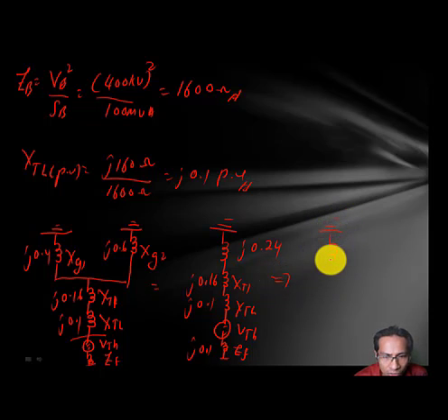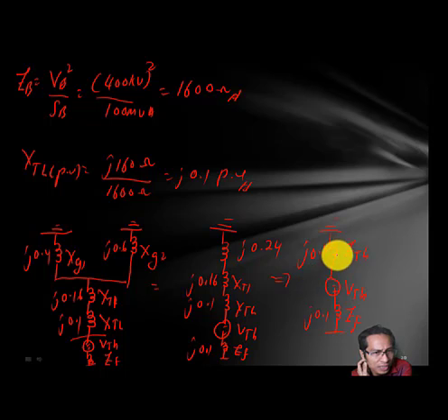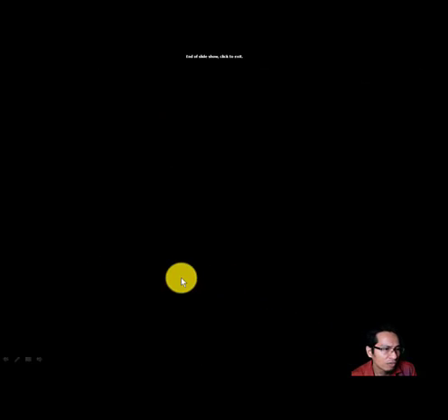So we simplify this circuit to become like this. Okay, we want to have this circuit only, minus plus VTH, this ZTH with this Z fault impedance, which is J0.1. So ZTH, we just combine this 0.24, J0.16, J0.1. So when we combine all this together, we will get J0.5. Okay. So to find the fault current, we have J0.5, J0.1.